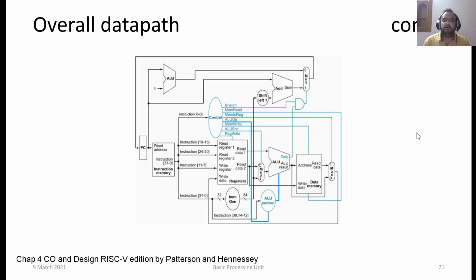The reason being, in the Computer Organization and Design RISC-V Edition book that we were following earlier, directly the figure on the slide is given. So it's a little complicated to understand if I present this right from the word go. But now you can make some inferences from this flow. Basically, here we have the PC that would be given to the memory, and the memory would be giving us the instruction, which is 32-bit, and different fields from this instruction are given to the register file. Basically, rs1 here, rs2 here, this is rd, and then the register file would give us the values A and B. Earlier here it is read data 1 and read data 2, and we had mux B earlier, here it is labeled as mux 1, right?